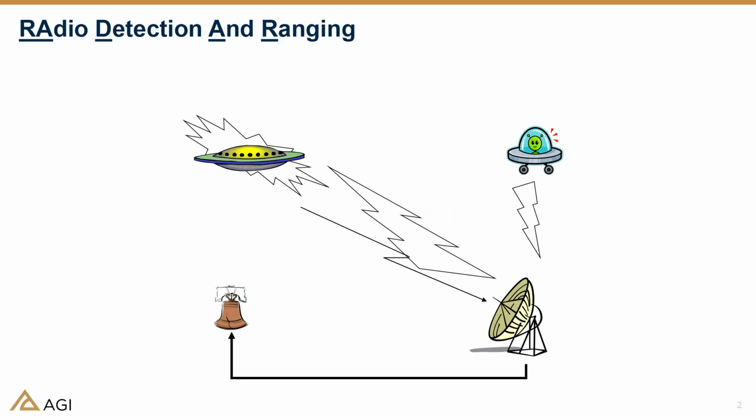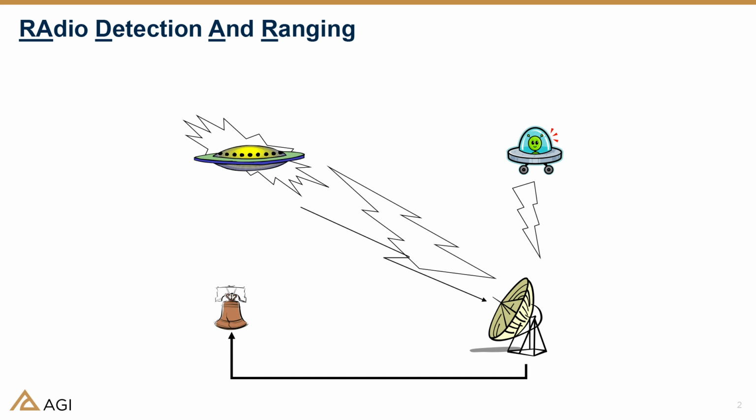As many folks know, a radar system essentially sends out a specific amount of power towards an object. As it sends out that power, a little fraction of it ends up coming back to the radar, and that is what it is detecting to determine whether there is some type of object in the air or approaching the radar.